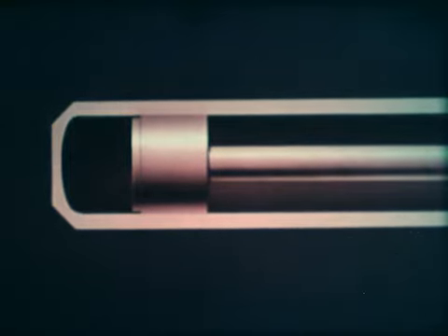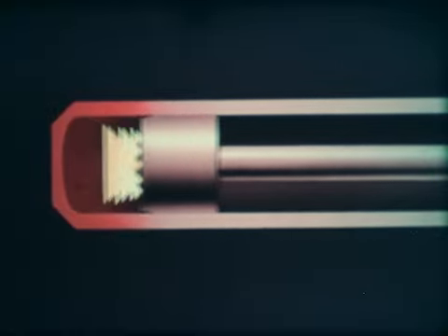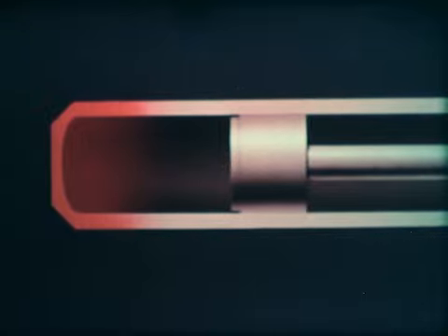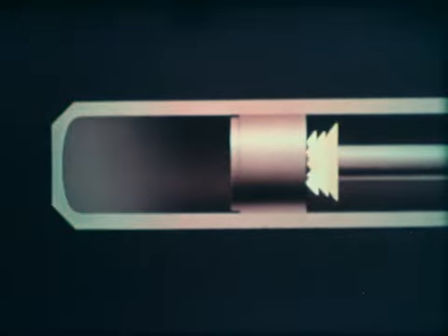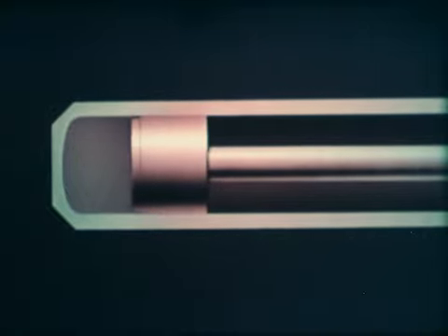The power can be increased by raising the pressure on both sides of the piston to a larger value. In the Philips engine, this may be 100 atmosphere or more. The forces induced by heating and cooling will increase correspondingly, as will the energy delivered per cycle.